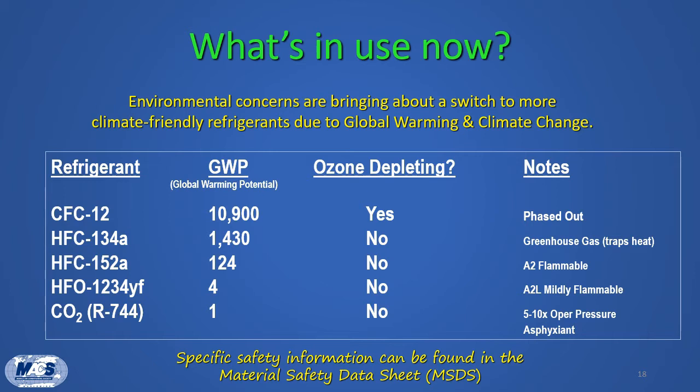As new model vehicle platforms have been developed during the past few years, global automakers have been converting many of them over to use the new refrigerant R1234YF. It has a relatively low GWP of 4 and must still be recovered like other MACS refrigerants. It is also classified by ASHRAE as an A2L mildly flammable substance.